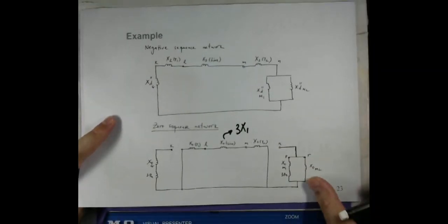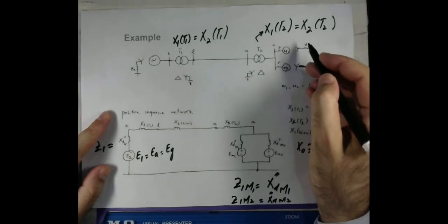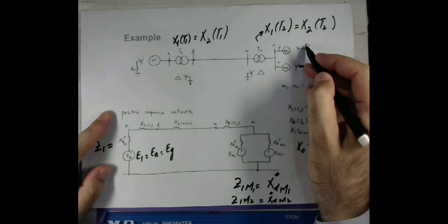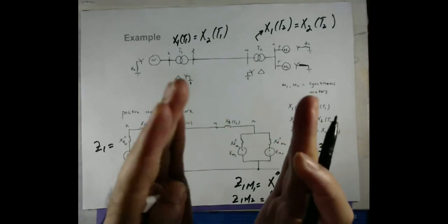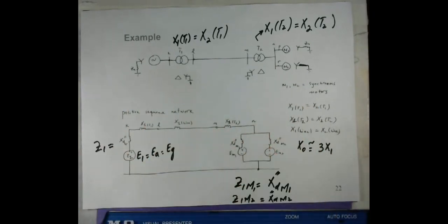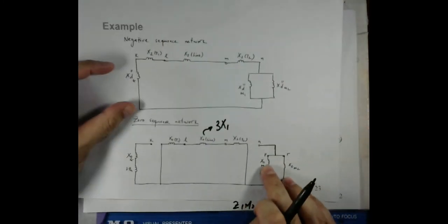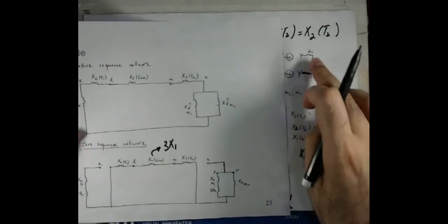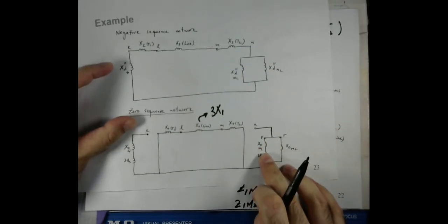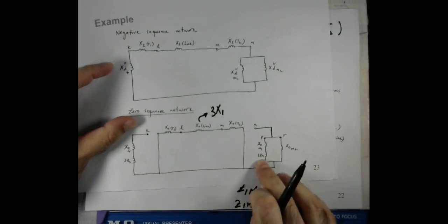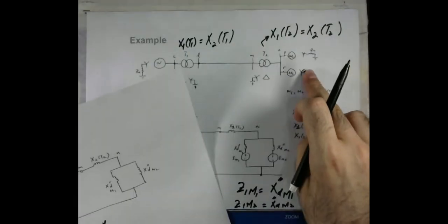Now once again, as I mentioned, we are talking about the zero sequence network, so this Zn has to be taken into consideration. We also have to multiply it by the factor 3, because in the zero sequence network, the impedance offered to the current I naught is 3Zn. Here there is no Zn. So for motor 1, we take the zero sequence impedance as X0 of M1 plus 3Zn, and for the second motor it is the same without Zn, because there is no Zn involved.